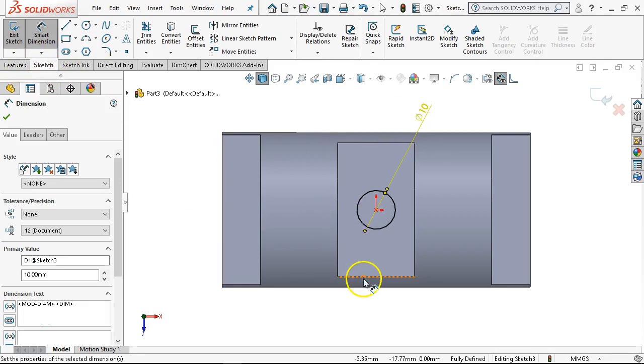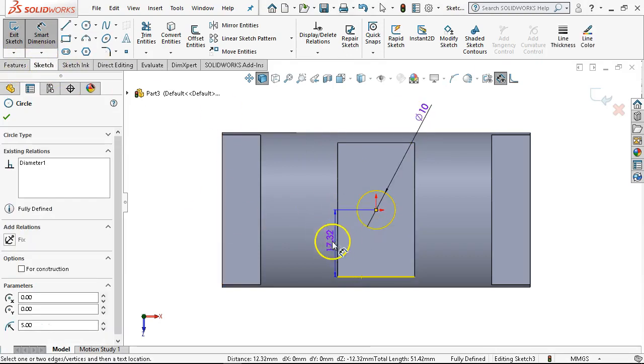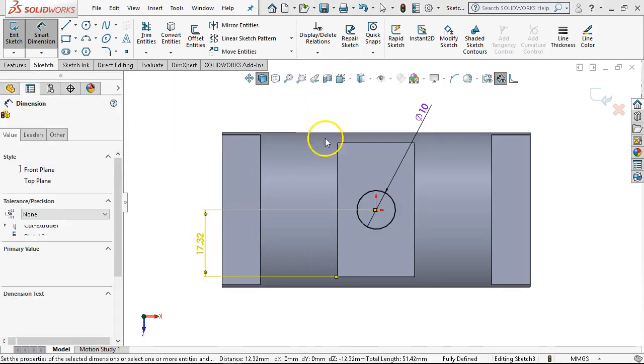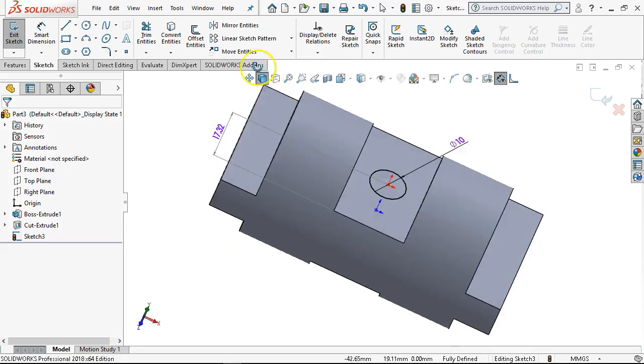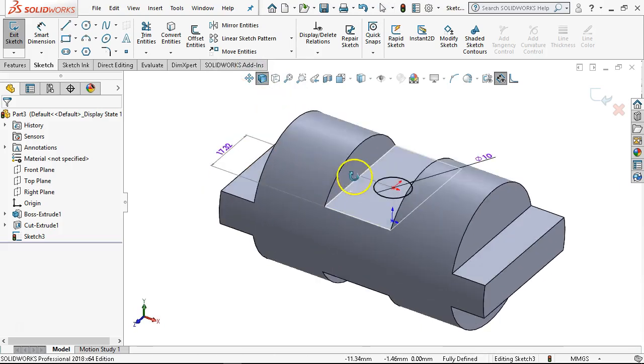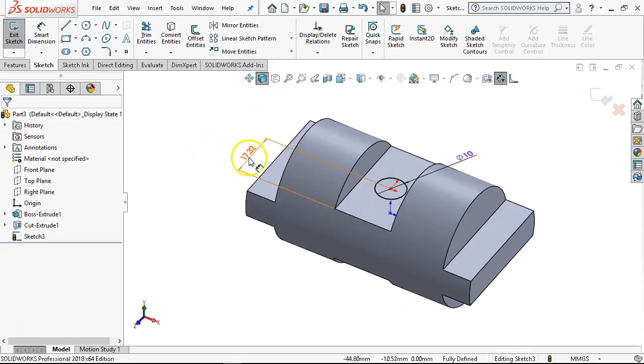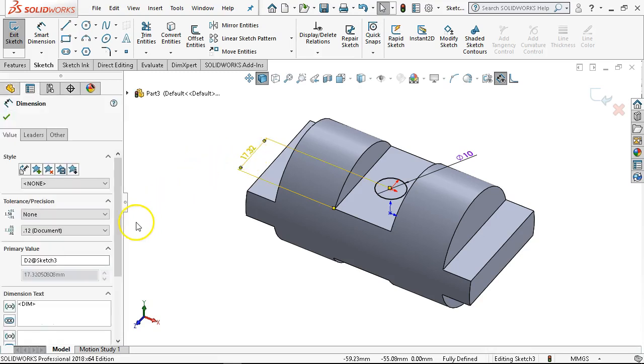And we're still in the smart dimension, so let's see if it's 17.32. Yeah, it's kind of got a rounding error to it, but if you want that on center line, I'm not buying that edge. I don't know why that would be off. 0.32 millimeters, that's what, 25? It's a lot. It's almost a 32nd of an inch. All right, so we're going to have some issues with that one. So that would be another one of those. Hey, it was in the drawing.